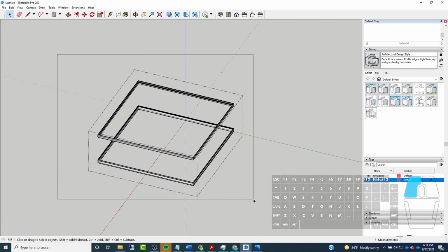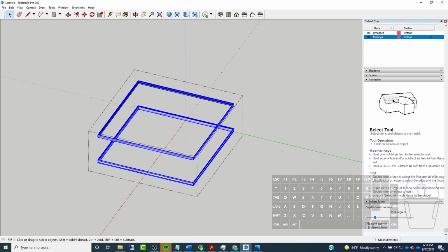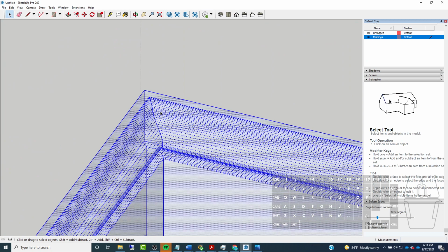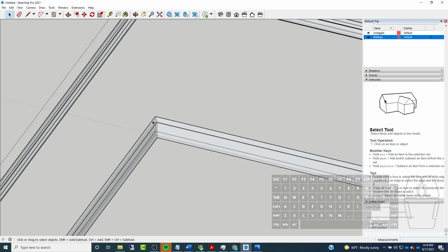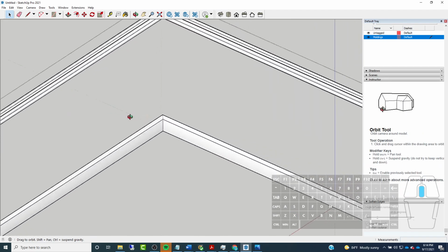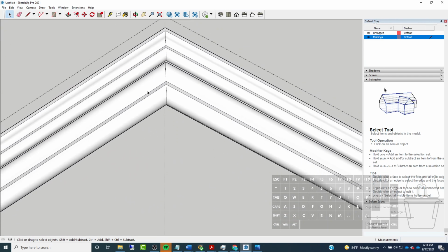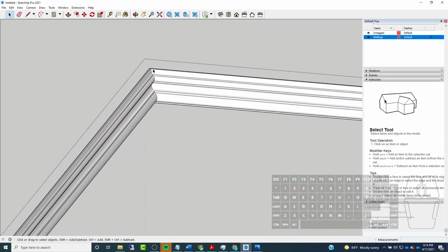So I'm going to select all of the geometry, and then go here to my soften edges and then just tap on this slider and slide it up a very small amount, and it looks like it did what I wanted it to do. So now if I click off of it and I click my X key to switch back out of X-ray mode, you can see I have nice geometry. And that looks perfect. Okay, so it's not too hard to add in all this complicated detail within your models.